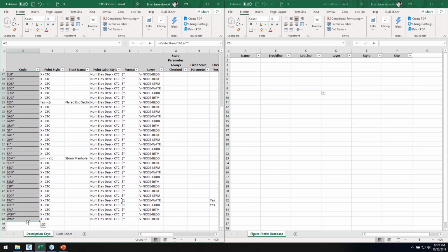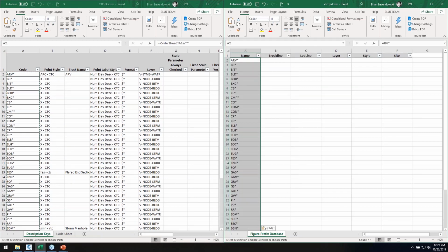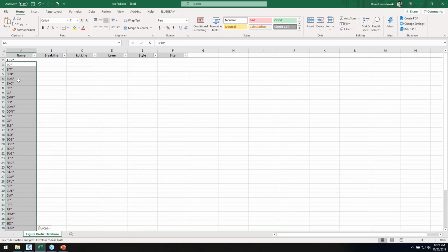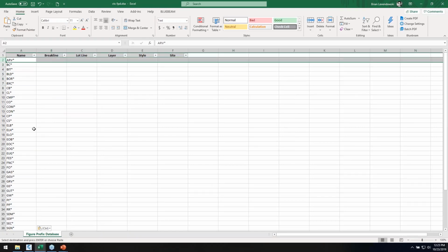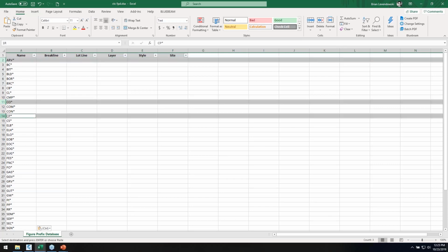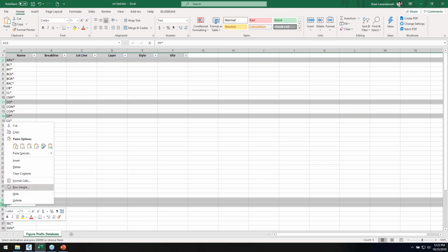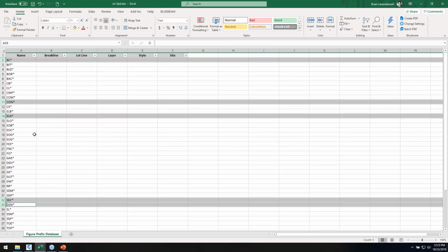Now we're not going to need all of them. We are going to want some. So let's paste them in and then just simply go through and delete out the ones we know aren't going to generate line work. So cleanouts, air release valves, control points, these types of things that are symbology that aren't going to generate line work for us. Okay.